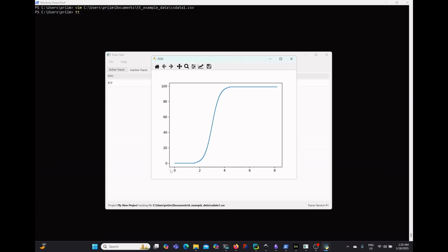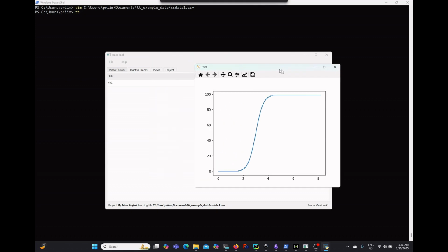Now, the other important part is that the y-axis, which is probably going to be voltage, is really an integer in a ChipScope CSV file, and it's some sort of a fraction of some scale. For example, this could be an integer from 0 to 255, 255 corresponding to 3.3 volts or what have you. Ideally, you want to be able to rescale this as well. However, that functionality is not available yet, and will be available in the near future.